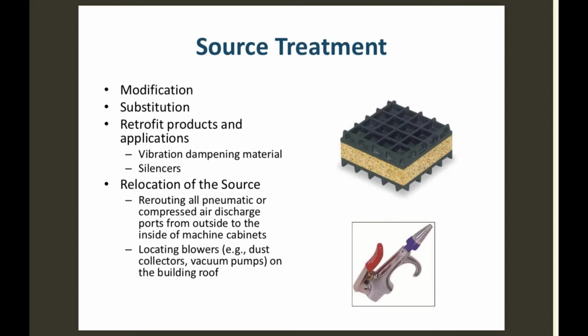Okay, so relocation of sources, routing of pneumatic or compressed air discharge force from the outside of machine cabinets to the inside of machine cabinets. So in other words, you've got to clean them apart. You put it inside an enclosure. You bring the high pressure air nozzle inside and use it in there so you can capture the...